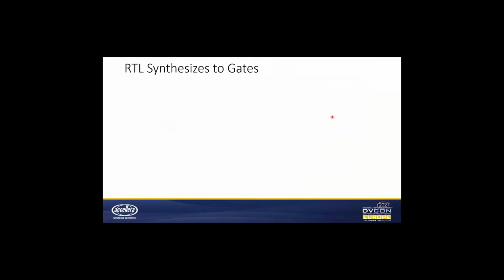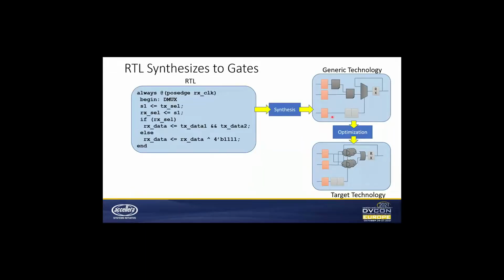In this slide, I will show you how clean RTL logic can introduce some CDC bugs or glitchy logic. Here the RTL is written for a demux crossing, and changes introduced in the netlist during the synthesis stage, such as timing optimization of synchronization logic, insertion of DFT logic, or low power circuitry, may cause incorrect behavior. For example, new clock domain crossings can be introduced due to insertion of low power logic. It may happen that new power domains are created and there are new CDC crossings.